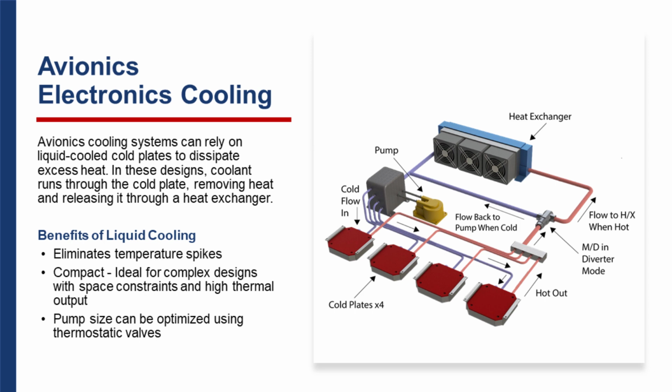call a reverse acting inline valve. And what that'll do is it will throttle it. If it's too cold coming out, it'll throttle it off. They'll let the other circuits that are too hot get most of the ethylene glycol or whatever media you have in there. So you can sort of optimize your pump if need be, and that would usually come into play when space constraints are very, very tight.